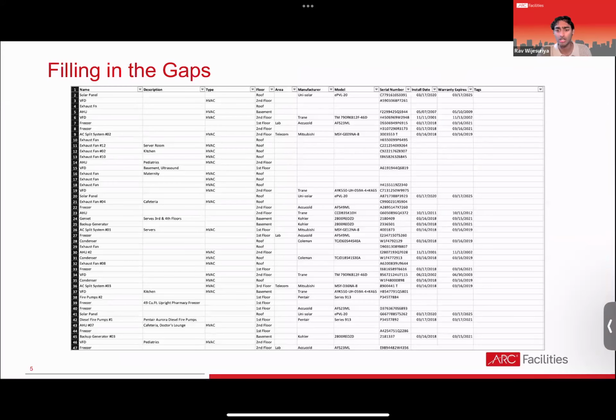This was an equipment list that we got from a work order system as an export when we were doing a field verification. And as you can see, there are gaps in places, whether that is in make, model, serial number, not collecting the panel details, or missing locations. But it's also more than just gaps of these small bits and pieces. It can be missing full-on equipment pieces, things that have been swapped out or added, as well as things that may need to be purged because this unit isn't even out there in the field. It was replaced 3 years ago, but we never had that opportunity or that time in the day to go back and account for that and establish a whole new field verified list.